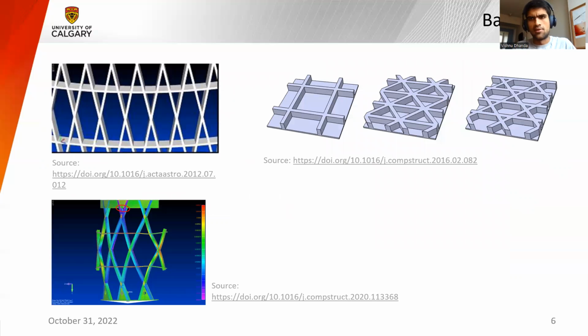What's been done? These are pictures from several research papers. What you find is that no one really models these accurately. No one's modeling the out-of-plane deformations that are seen, and no one is modeling the fiber bridging that's occurring. The end result of this is you end up with really poor FEA. The picture you see at the bottom there is FEA being done for one of these parts, and you end up with really bad results because you don't have accurate geometries.